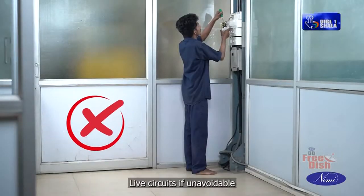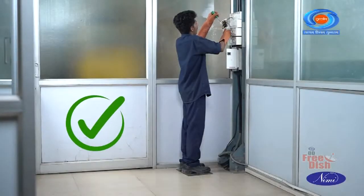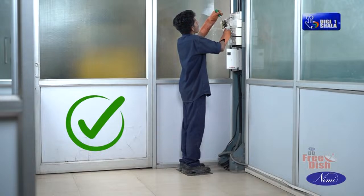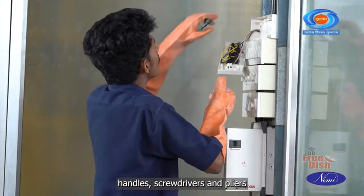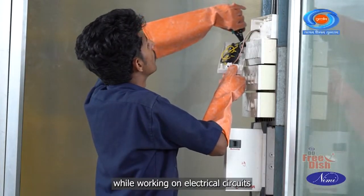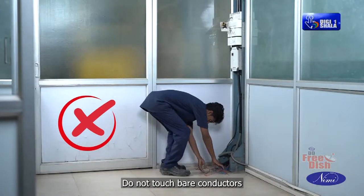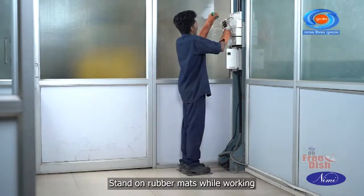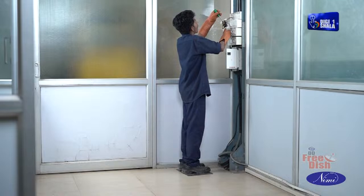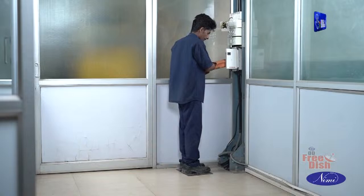Do not work on live circuits. If unavoidable, use rubber gloves, rubber mats, etc. Use insulated handle screwdrivers and pliers while working on electrical circuits. Do not touch bare conductors. Stand on rubber mats while working, operating switch panels, control gears, etc.